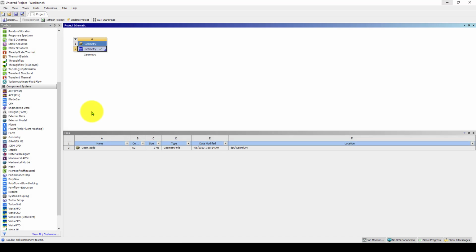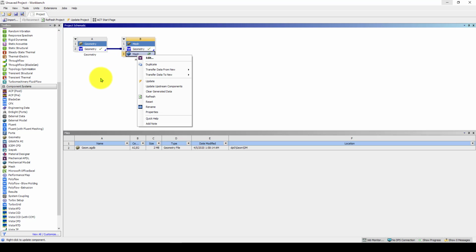And then we want to go to the mesh model. Here again you have it: mesh, drag and drop. You drop it here onto your geometry, and then when you have this symbol, it means it requires an update. Right click, and you go here, update. Basically it's just transferring the geometry into this format, and then you can use it.